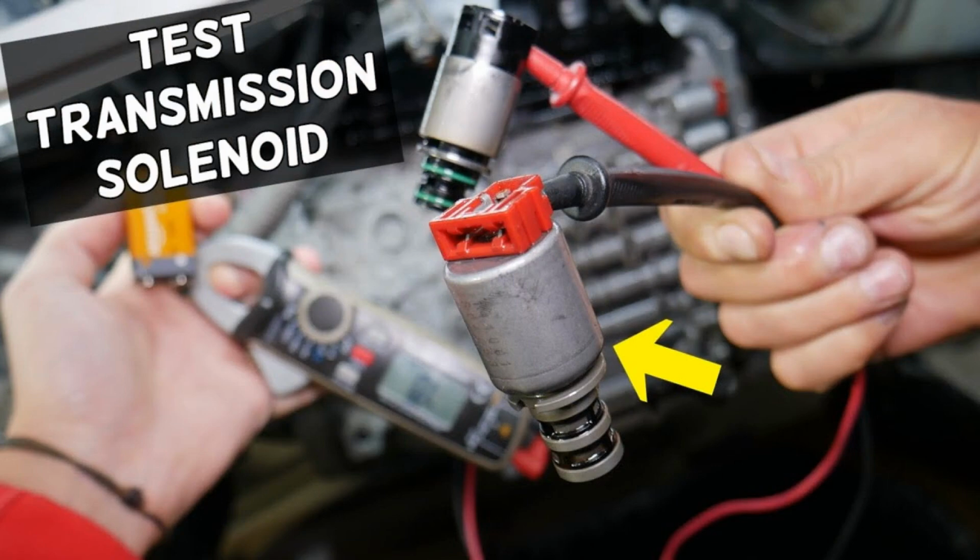Three-way. As the automobile industry was rapidly developing, solenoids operating on the simple on-off principle began to be gradually abandoned. Already in the 90s, three-way devices appeared. This is a new generation of switch. When in the on position, the valve ball opened the fluid passage from channel 1 to channel 2. By switching to the off position, there is a transition from channel 2 to channel 3. This innovation made it possible to disengage and engage the friction clutch as needed with a single device.